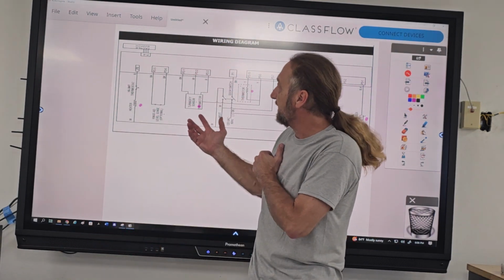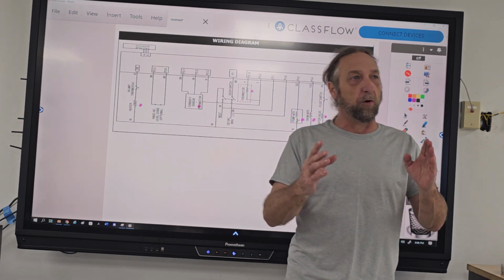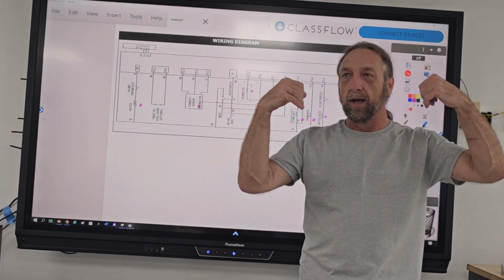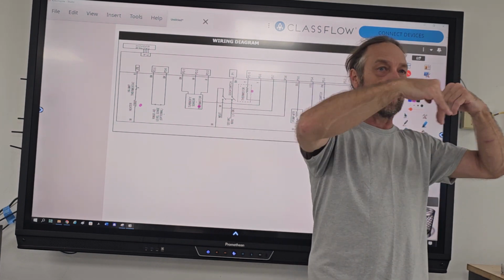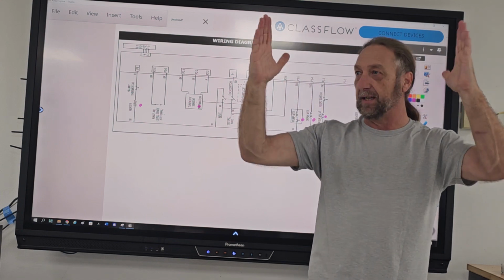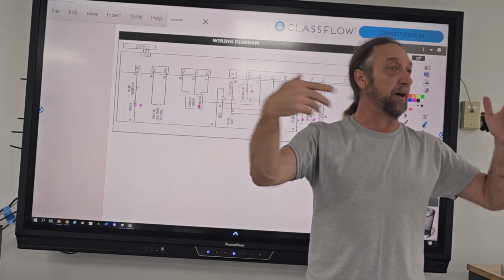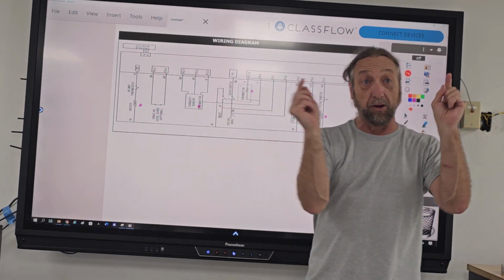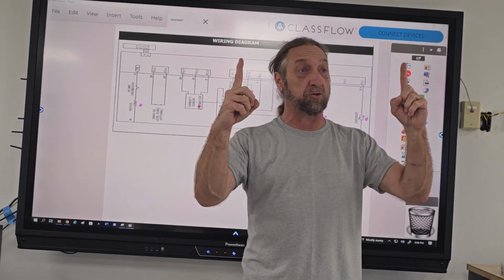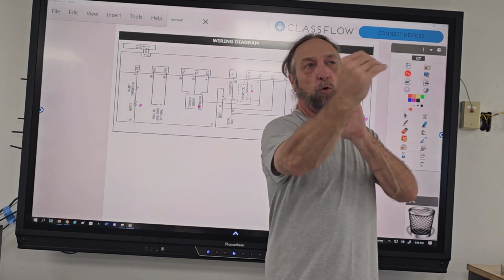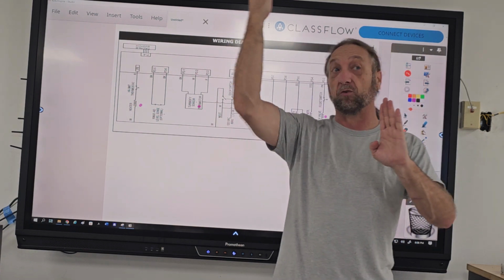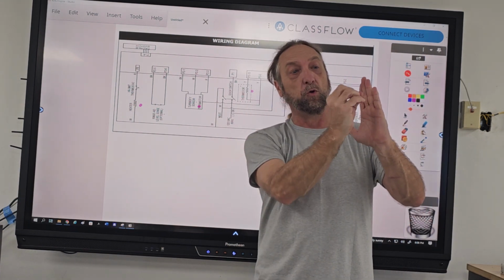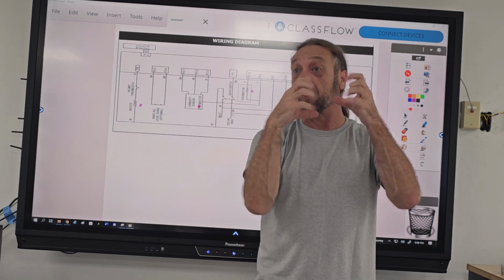So the turbidity sensor, like we said before, is like when you walk into a store and it beeps as you pass through the gate, like you cross an infrared line. That's what a turbidity sensor is. It's got a little infrared beam between 2 posts, and the water's forced through there when it recirculates through the pump. As the food goes there, it blocks that infrared and creates a pulse.